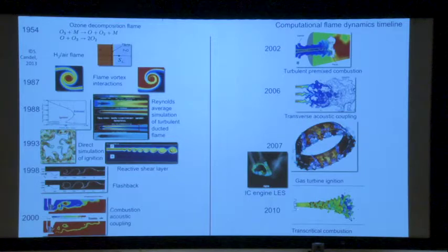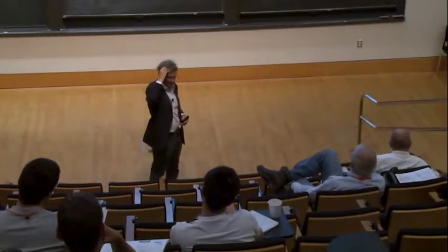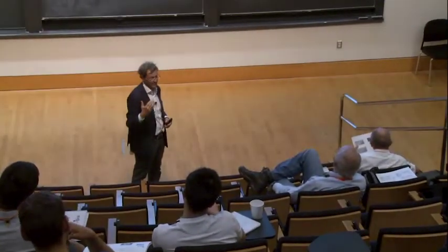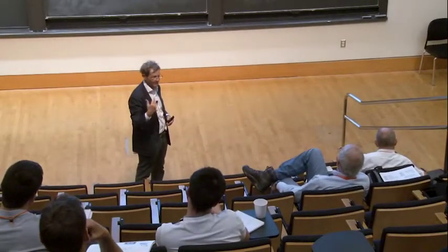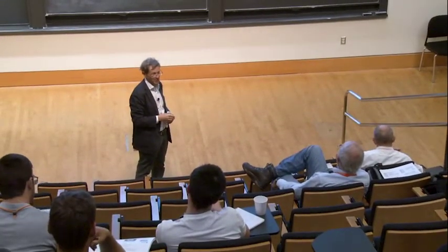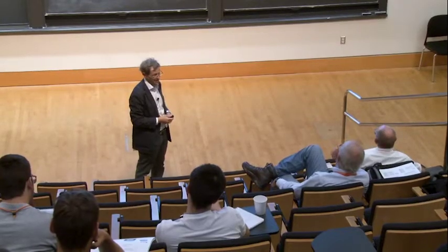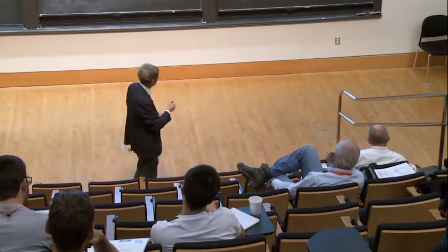And we worked also very much on combustion at very high pressure in transcritical situations, above the thermodynamic critical point. This is fuel, and this is oxygen injected at very low temperature and high pressure, above the critical point of oxygen. This is difficult because then you have real gas effects, another complexity, and we are now able to calculate such flames.